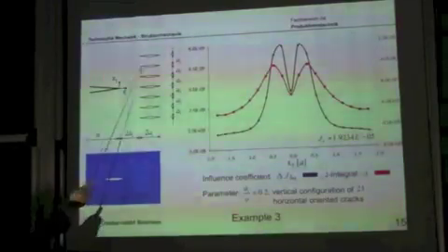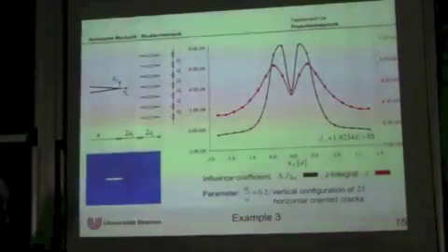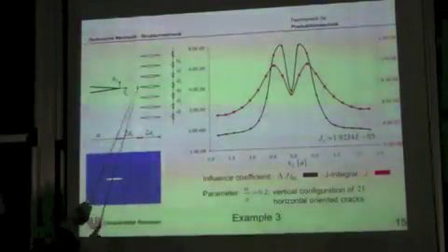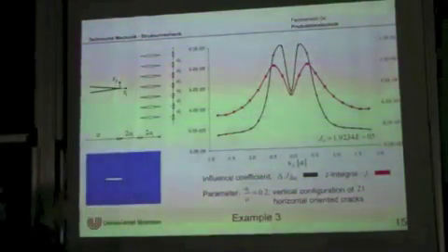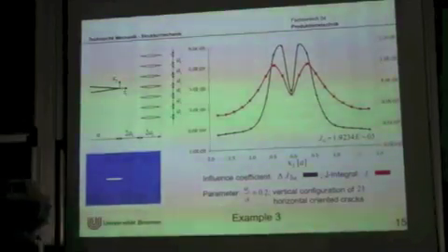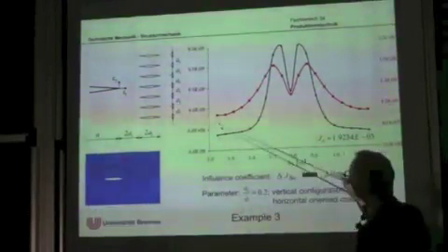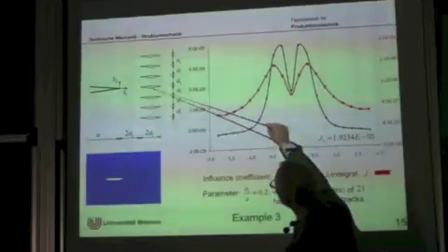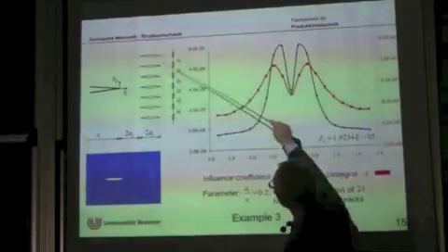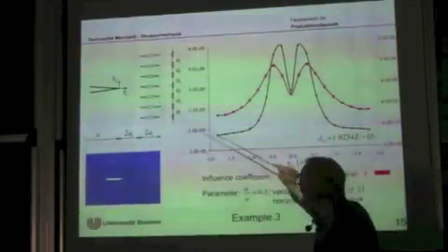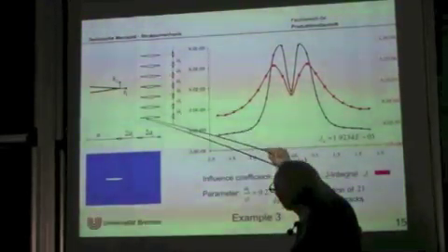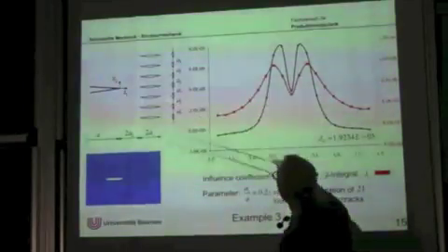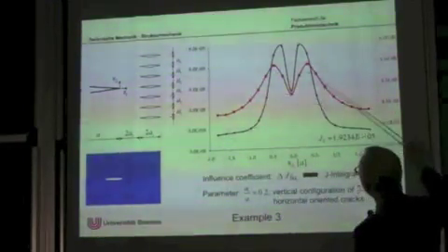Okay, we have to understand what comes out. You have all these small cracks here, 10 up and 10 down. And first, so that you get an idea of what happened, we calculated the individual J1 integrals if we apply stress in this direction. And this is the red curve. What you see is the position of the crack going from here to the symmetry plane, and you see that the J integral of the individual small cracks due to the presence of the large crack is distributed in this way, like the red curve.